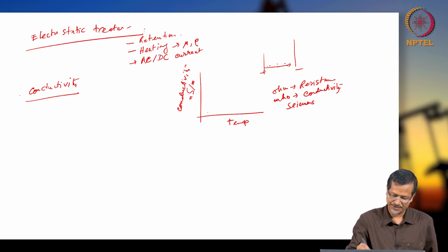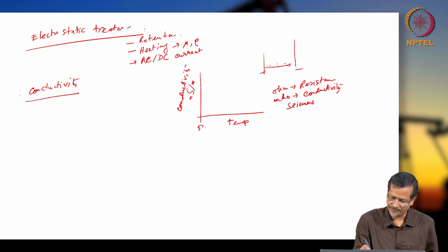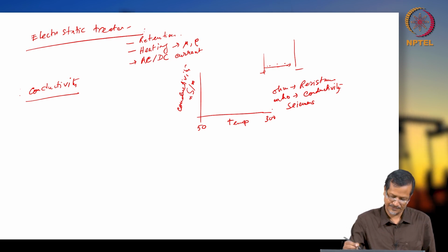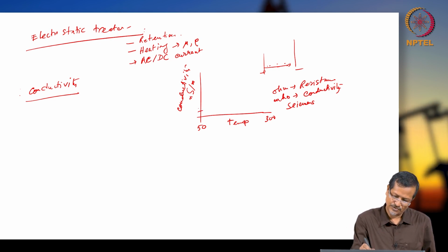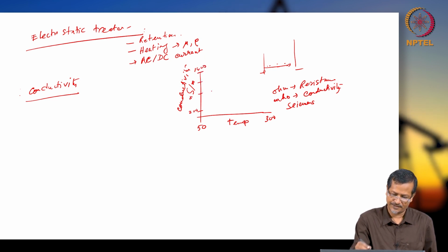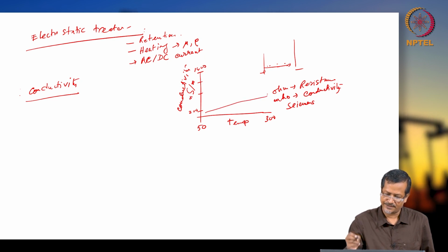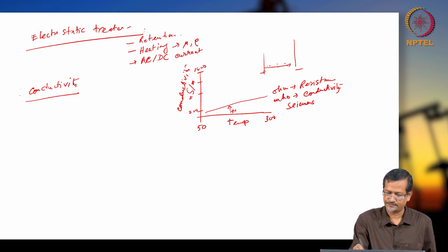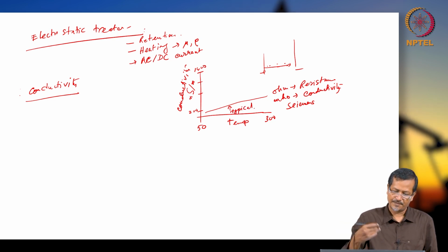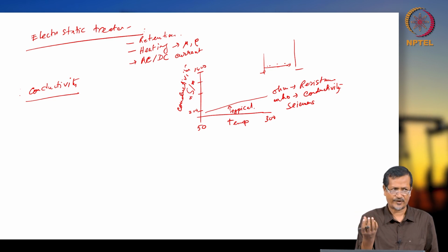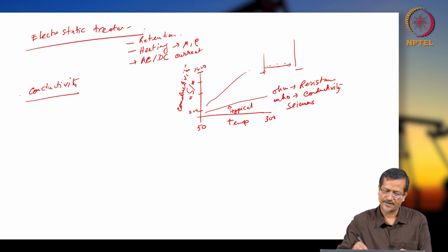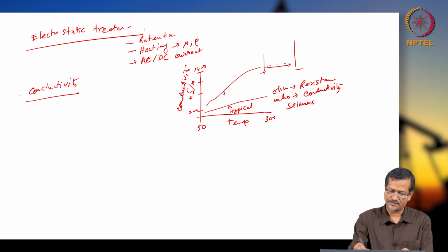So for temperature, they have taken a limited range within 50 to 300, and conductivity they have written 200 and 1400, so 700 another division you can do, and it is becoming like this. This is a typical curve. As temperature increases, conductivity increases, but in some cases a very high amount of ionic salts or ionic material is there in the oil. In that case your conductivity can go very high also. So this will be a very high condition.